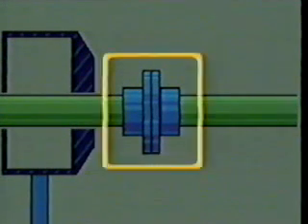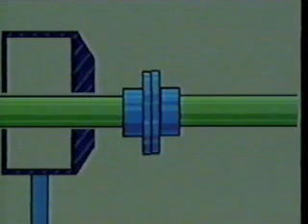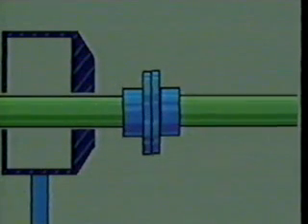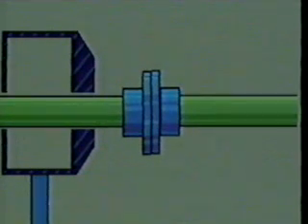You already know that on most centrifugal pumps, couplings join the shafts of the driver and the pump. They have to be flexible enough to handle misalignments between the shafts, as well as changes in the driver's speed. Alignment of both shafts is critical for good, smooth operation of the pump as a whole. If they're not aligned correctly, the shafts and other pump parts will vibrate. If that vibration gets serious, it can put enough pressure on the shafts and couplings to break them.